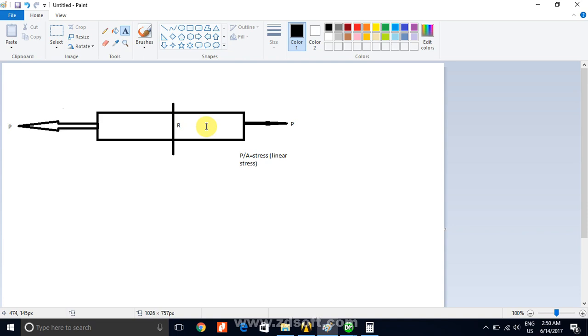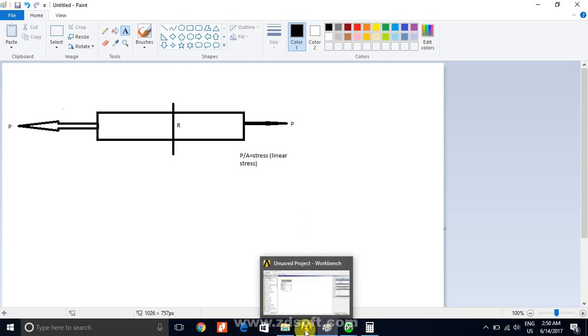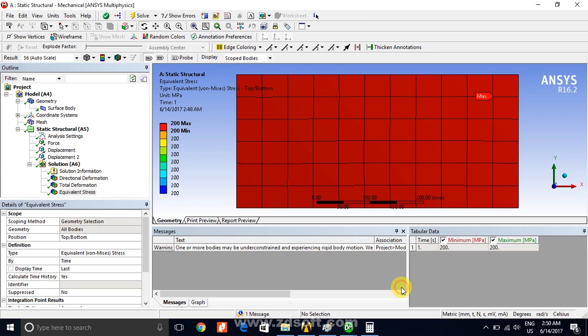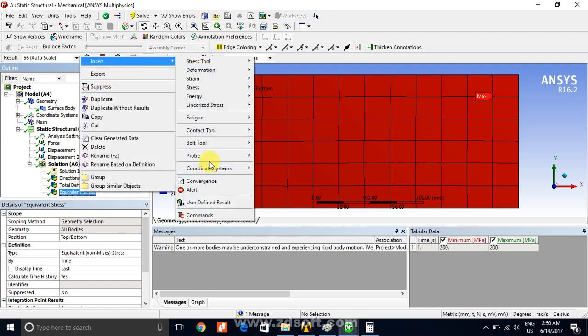So this would be the same throughout the body, and we have the capability to avoid the effect of boundary conditions, so it is very good that we have done it here. We have modeled it in such a way that we have avoided the effects of boundary conditions, and we get the 200 value throughout this body. So this is really nice, and you can also study the convergence of this stress value.